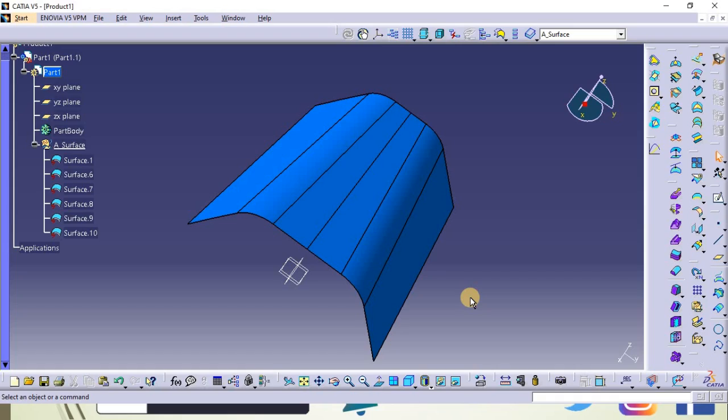Once the concept design is approved, which is usually a hand sketch done by designers, a clay model is prepared which will resemble the final vehicle to be launched. This clay model will be to the actual scale of the final vehicle.